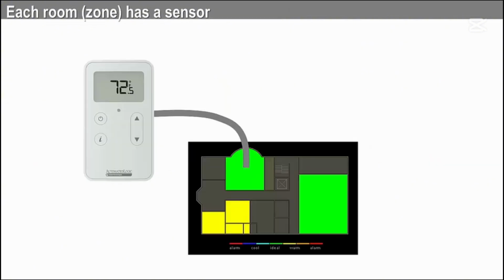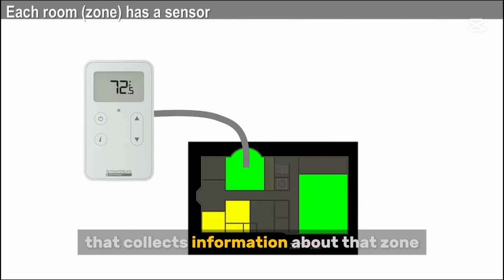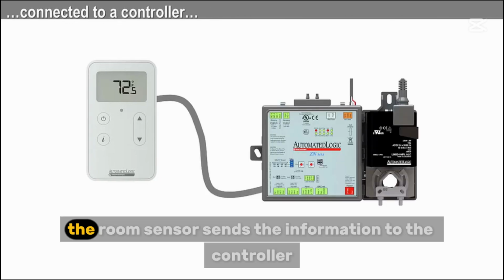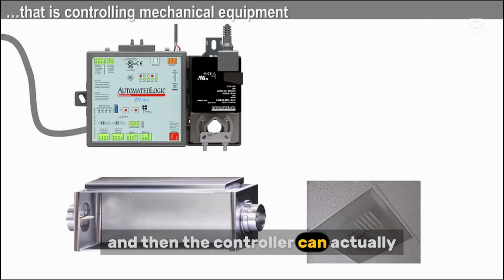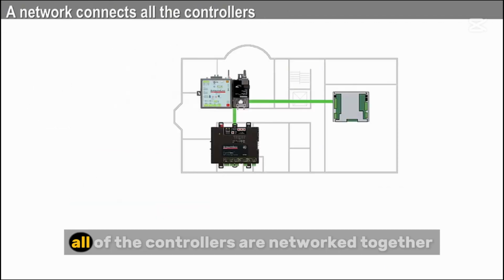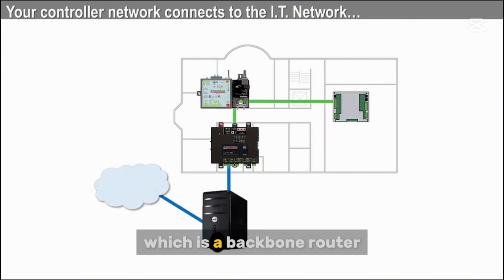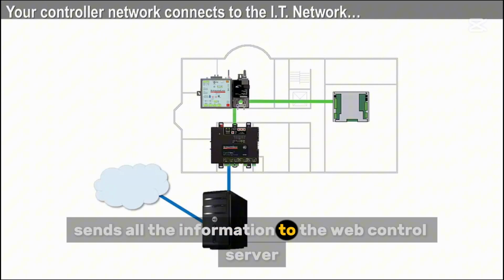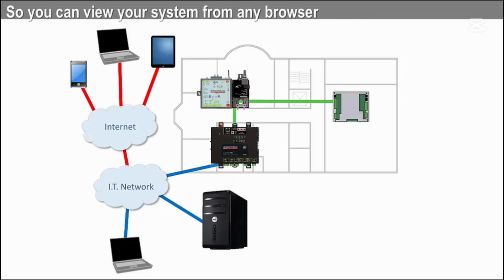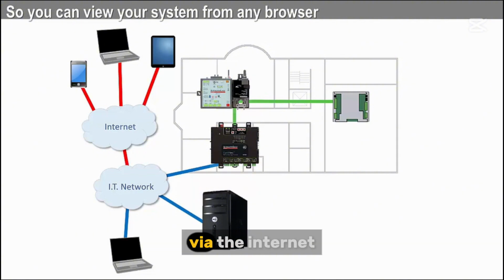If we look at it from a different angle, each zone has a room sensor that collects information about that zone. The room sensor sends the information to the controller, and then the controller can actually control a physical piece of equipment with its outputs. All of the controllers are networked together. And then a special controller, which is a BACnet router, sends all the information to the web control server. If allowed by IT policy, it is possible to connect to the web control system from anywhere in the world via the internet.